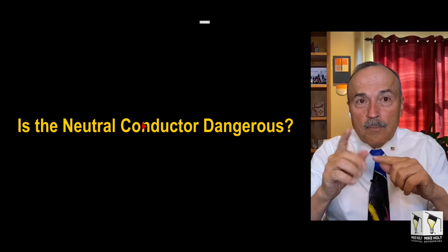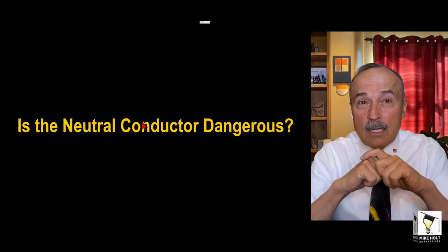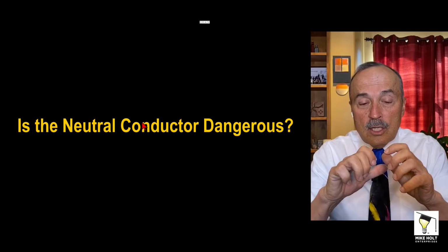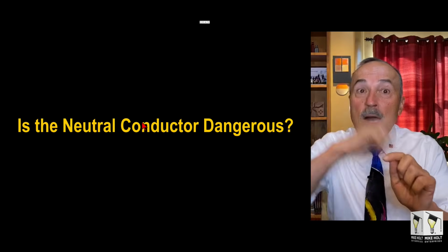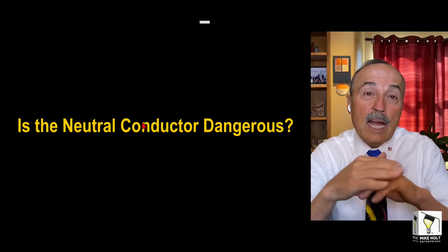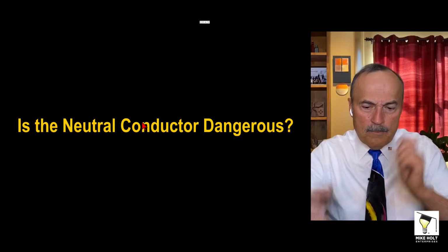Well, I hooked up the brown, the orange, the yellow, put my arms down, felt good. Took my side cutters, put them on the side of that 1900 box or 4-square, whatever you call it, and cut into the neutral conductor coming from the office. I got nailed. So yes, the neutral is dangerous, but let's understand why.